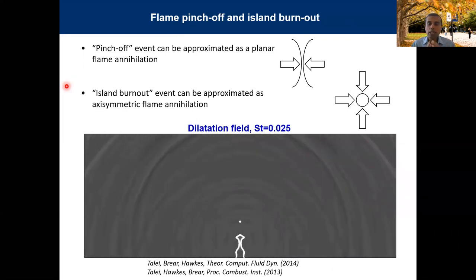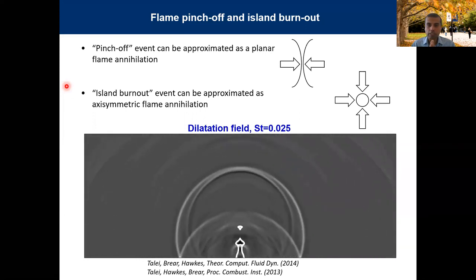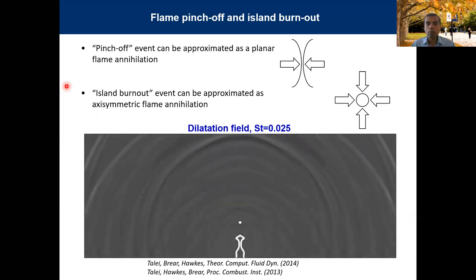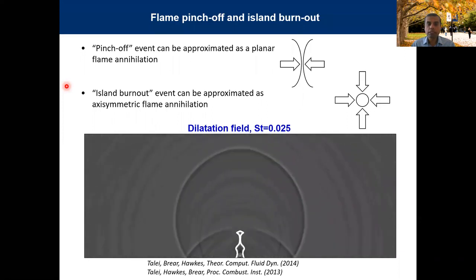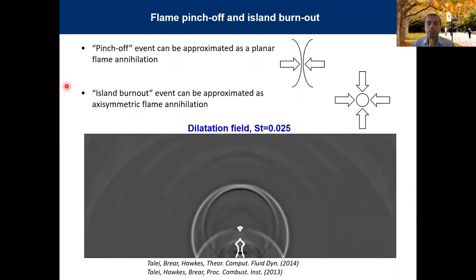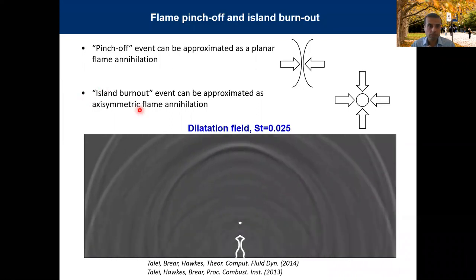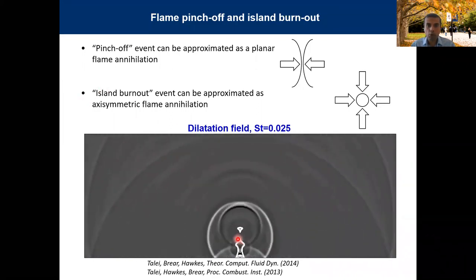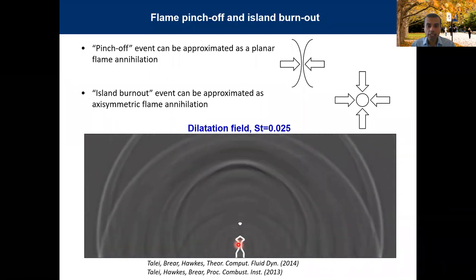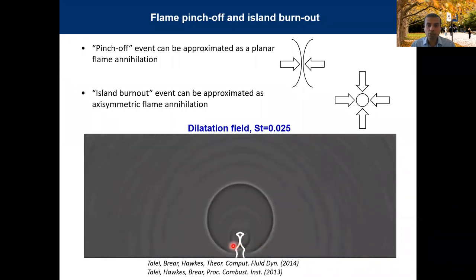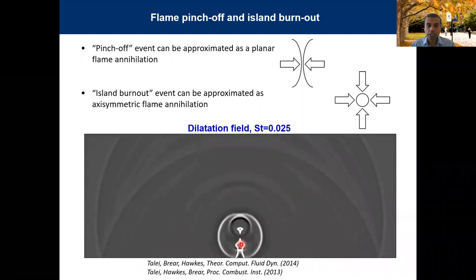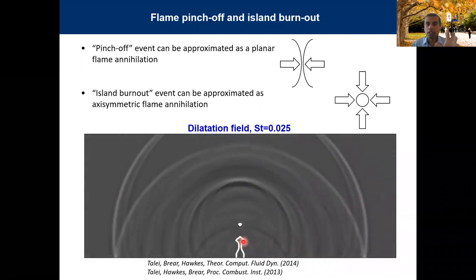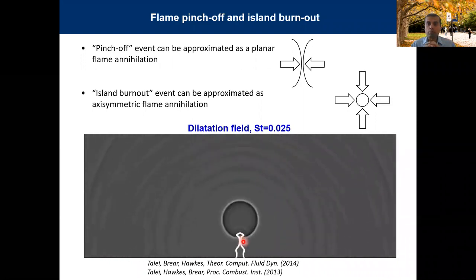So if you look at this flame, which I said is excited at a certain frequency, a couple of things happen here. So at some instant, you can see that the flame surfaces, if I can show it with my laser pointer, the flame surfaces here collide with each other, and you can see that this is a strong source of noise, okay? So when the collision happens, you have a big circular wave being generated and propagating to the far field.